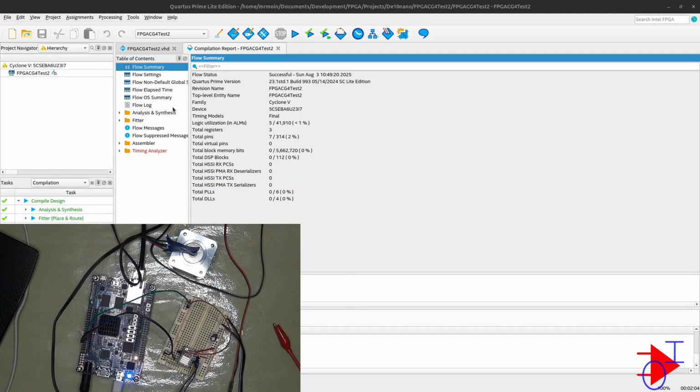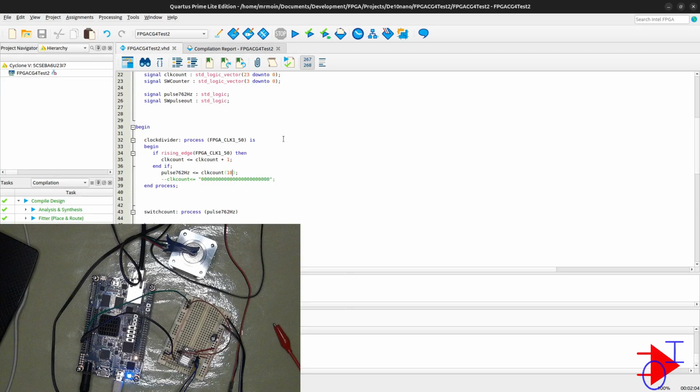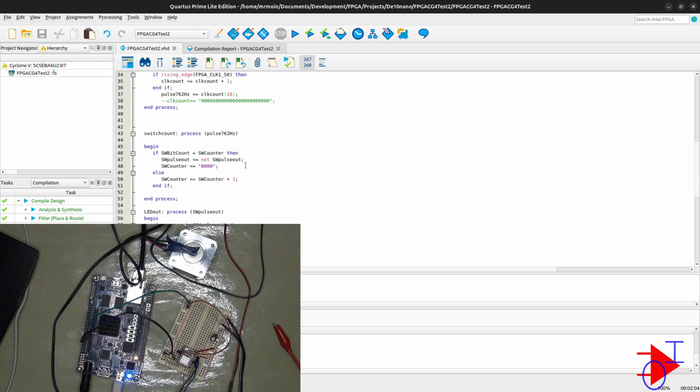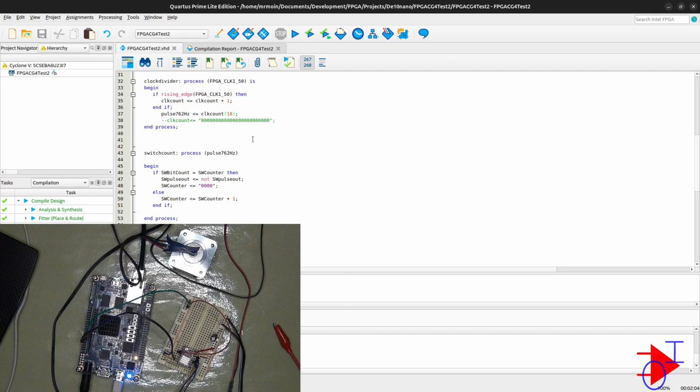Folks, this is complete. However, I have found a small mistake in my code, and that is basically where the counter is counting up. I should have a second condition to confirm that it is not overflowing. At this stage, where the counter is matched and we are pulsing, in my previous code that I tested, it worked flawlessly, it actually had a condition to prevent the counter from overcounting.